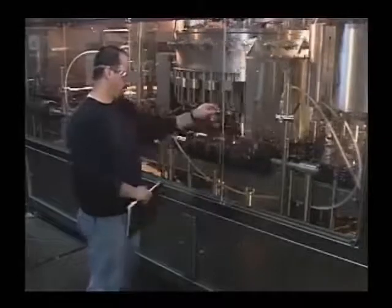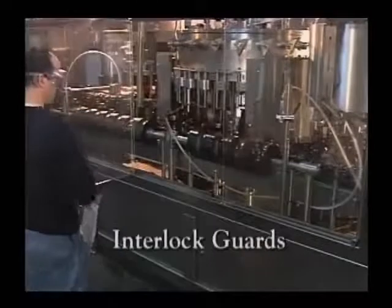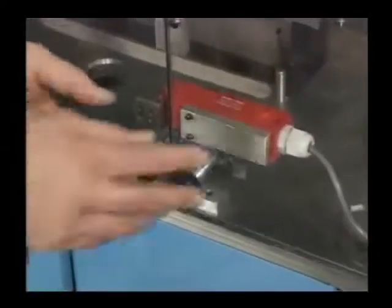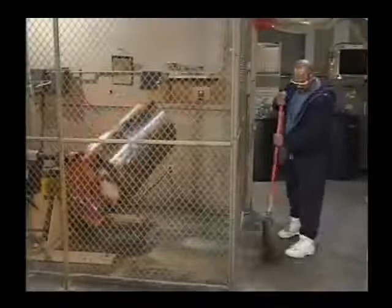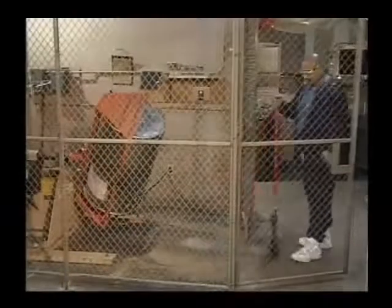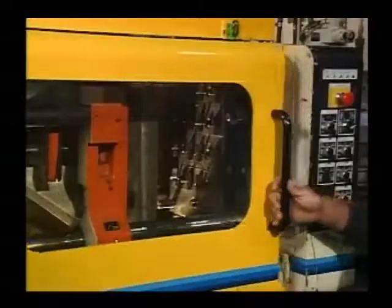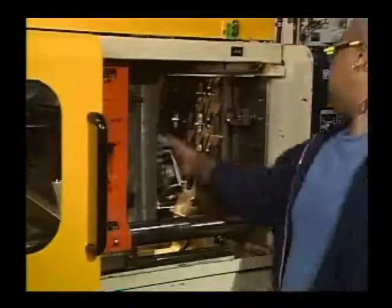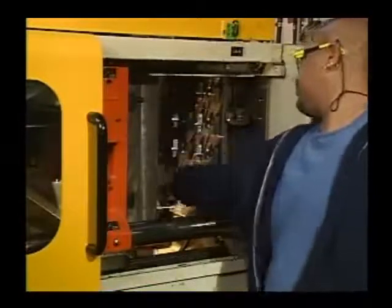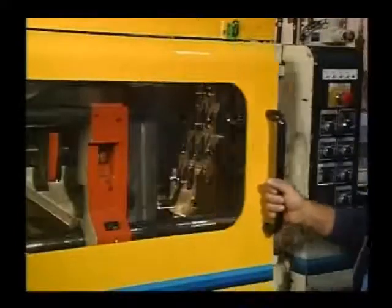In situations where fixed guards don't work well, interlock guards are often used. These guards use electronic sensors that will not permit a machine to run unless the guards are in place. This provides workers with complete protection while at the same time enabling safe access to all machine areas. When an interlock guard is opened, the sensor trips a relay switch that shuts off the machine's power. When the guard is closed, the power returns, and the machine can once again be operated.